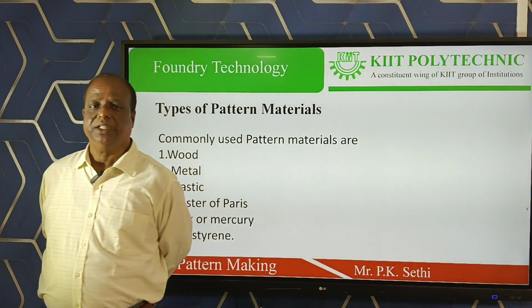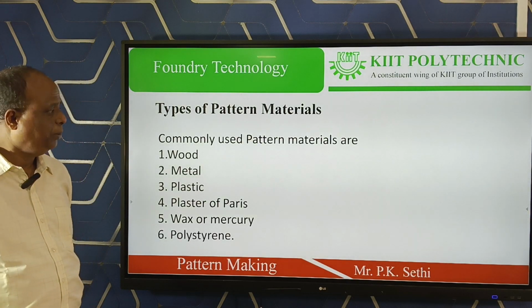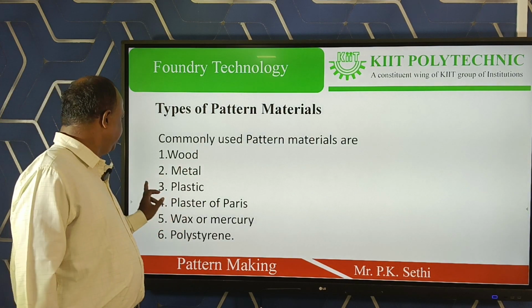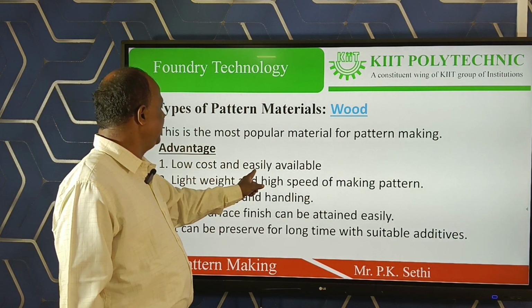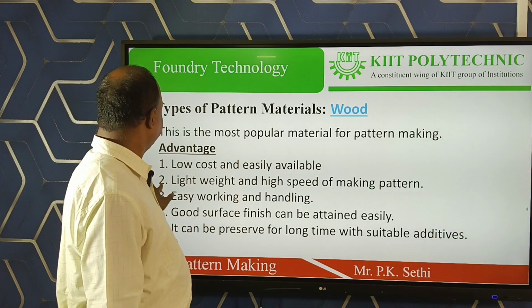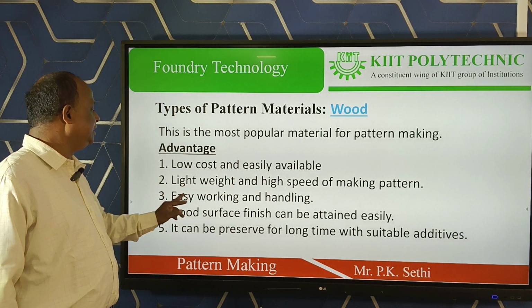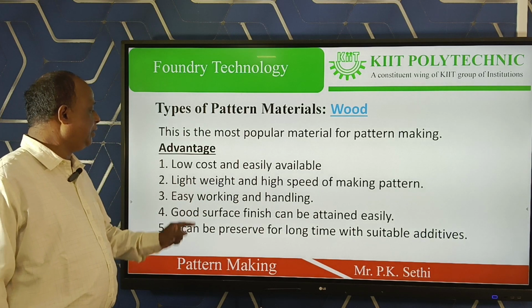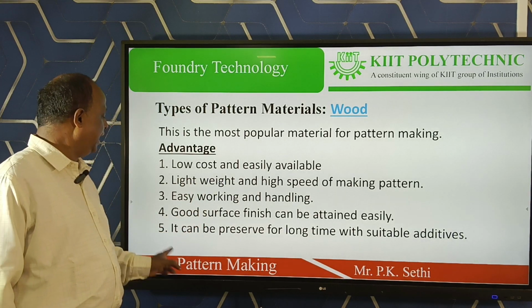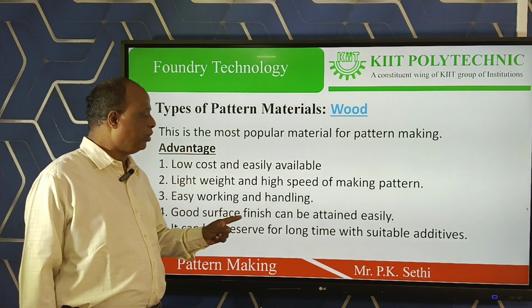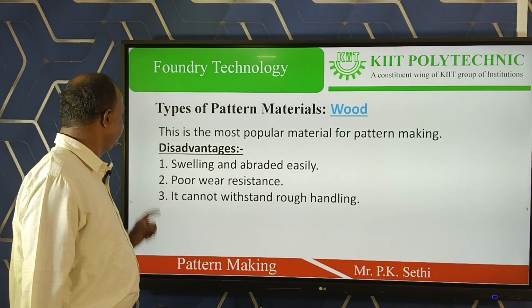That is why generally the pattern is made of wood. These are the advantages of wood patterns: first, low cost and easily available; second, light weight and high speed of making the patterns; third, easy working and handling; fourth, a good surface finish can be obtained easily; fifth, it can be preserved for a long time with suitable additives.